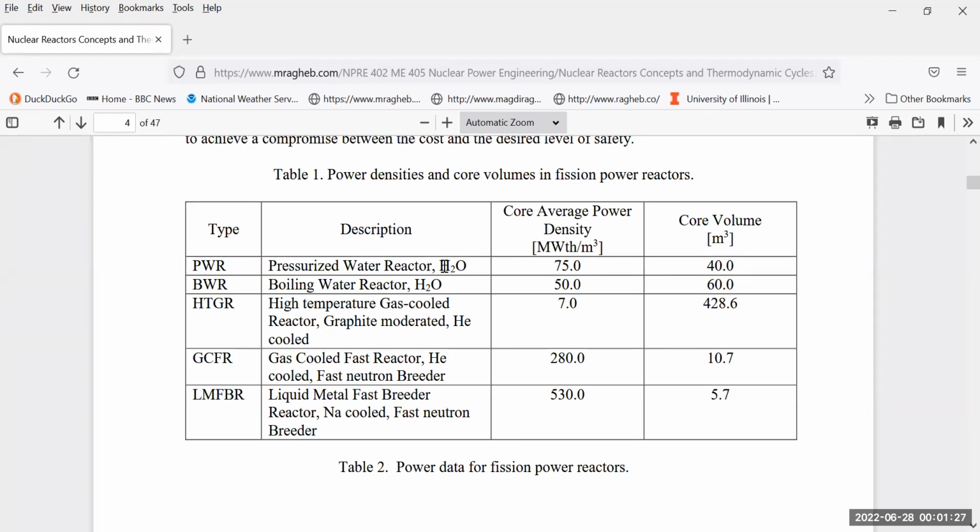In a liquid metal, instead of using water or helium as coolants to reject the heat in the flow system that we have to establish in that type of design, and all designs, in fact, you use liquid metals. And one of them, a choice one, is sodium. Sodium at room temperature is a metal, of course, that is a solid, but when you heat it, it becomes a liquid. Sodium is not as good as hydrogen in water or graphite, carbon, in thermalizing the neutrons.